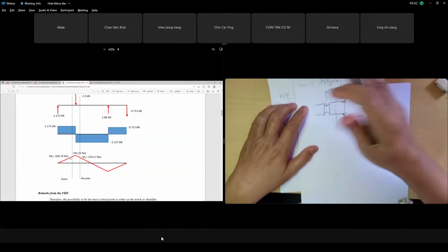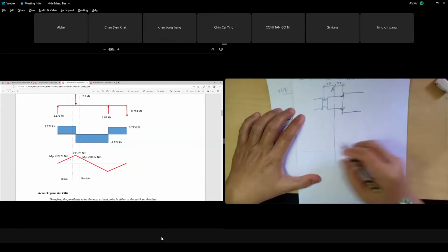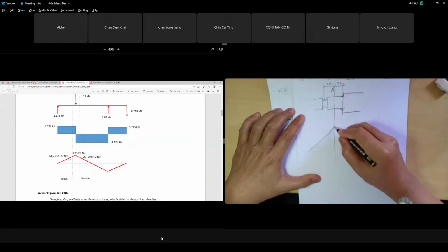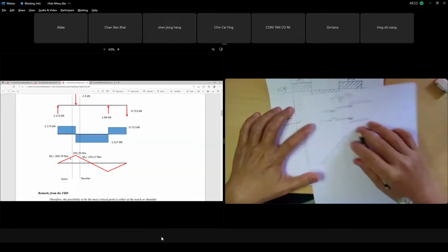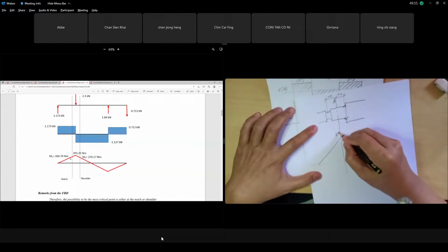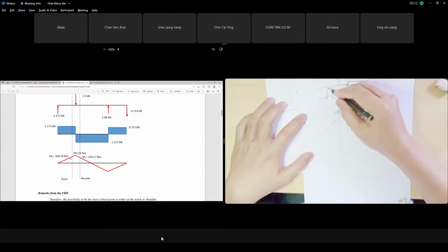Okay, class. So that's why in your moment diagram we have the peak MA, and it goes down here. MA we found out is 293,250 Newton millimeter. This is your moment diagram. So for 20 millimeter to your right, you offset. You use the theorem Pythagoras I explained to you. They found out it is 270,170 Newton millimeter, also the 20 millimeter offset to the right.